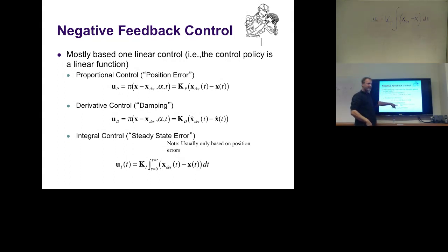But if you have an integral term, you fall down, but now you have an error left. This error starts to get summed up: you take this error, multiply it with k, and create a motor command. It will get you a little bit up, and you go up, up, up until you finally reach the goal. Again, we'll see this in an example in a moment.